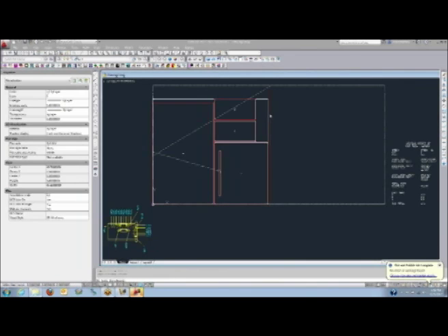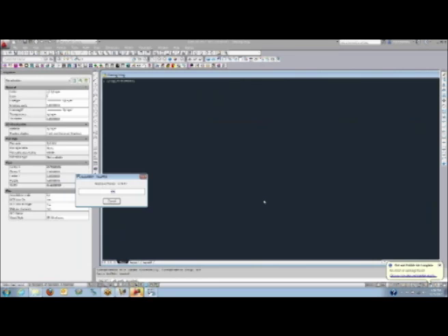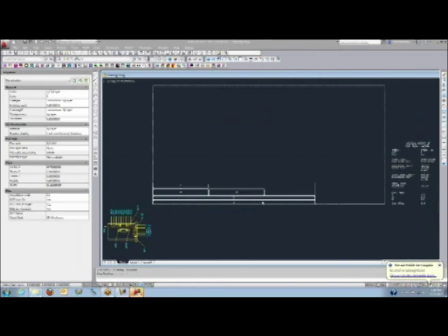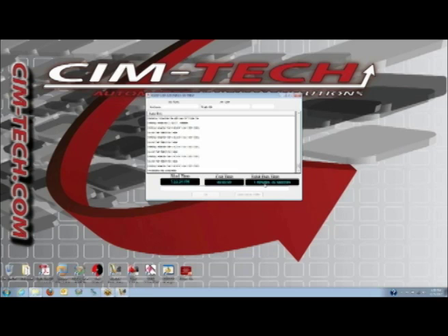Each of the materials gets nested with a scrap cut. If there's extra material left over, that is cut as a piece of scrap, optionally inventoried and used in the next job. AutoCAD has that rolling scrap manager built in as well. So in just a few minutes, we went from the Inventor assembly to nested parts and single part programs in 2 clicks, at about 2 minutes time.